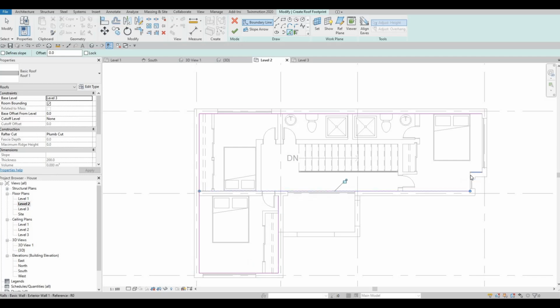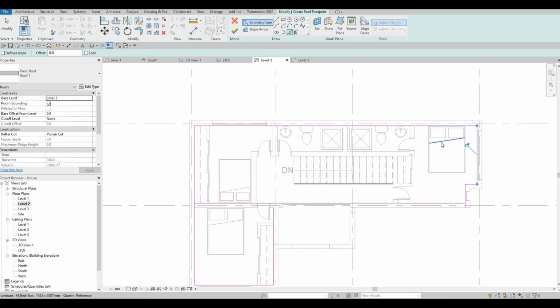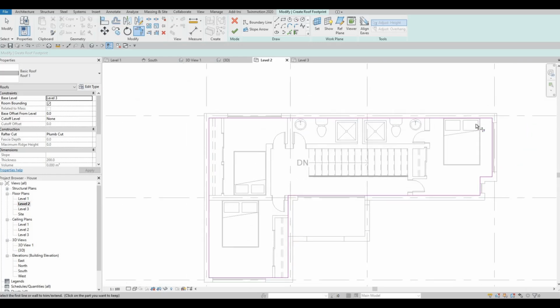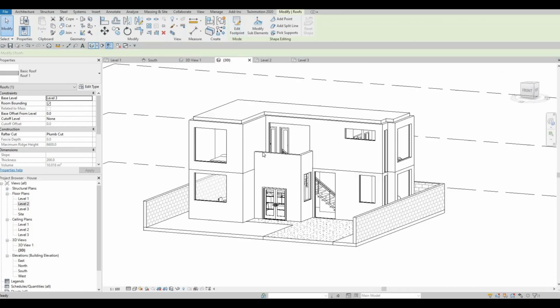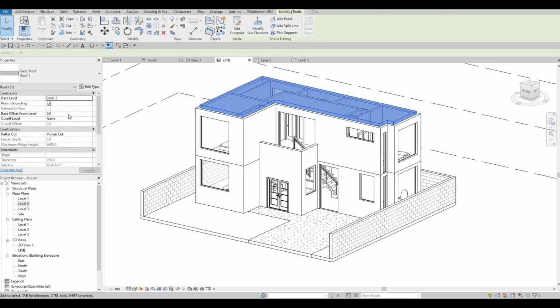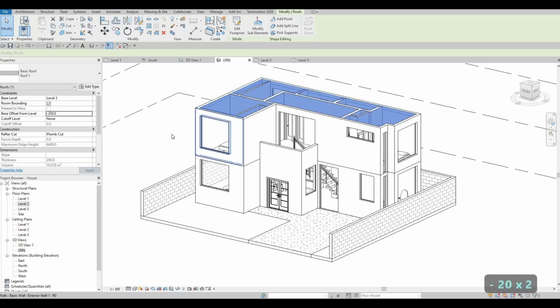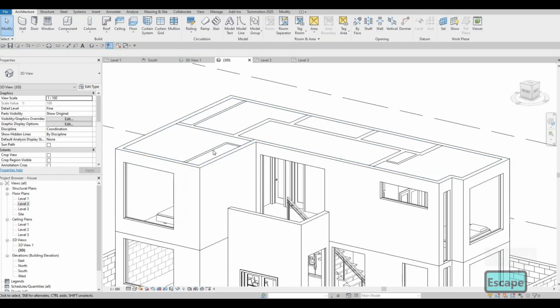And then once you do, go to the perimeter, the inside of the wall, and then now type in TR to clean it up. And then just double check everything. If everything is done correctly, click finish, and let's look at it in 3D. For this one, let's offset this to -200. That's the thickness of the roof, so that it's flat like that.